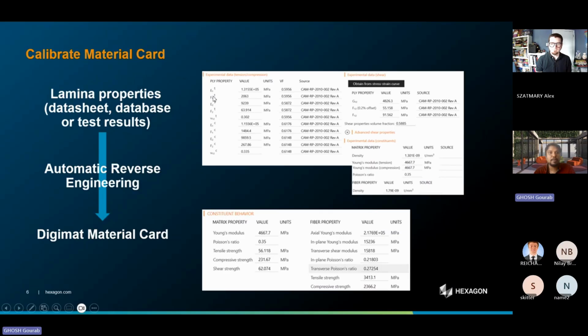here we want to have the ply properties like the Young's modulus and the failure strengths. Those things you can get easily from ASTM standard tension tests. And then we need shear tests to get those shear properties. So these are the basic tests. We have an extensive document, the Digimat user manual, which lists all this information. If you want to dive deeper or just contact us, we can discuss more. Depending on your needs, we can suggest which way you should go.